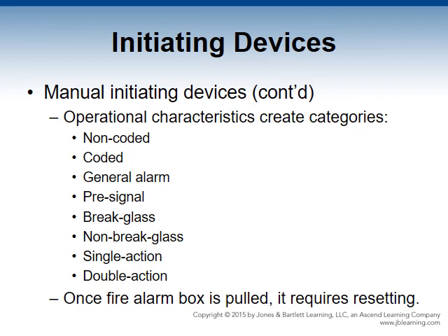Once a fire alarm box is pulled, it requires resetting. The fire alarm system will usually not reset until it is back to a normal or ready service. Usually the box must be opened, often with some sort of special key or tool, and then a switch may be needed to reset or a rod may need to be replaced. Oftentimes you can find these components somewhere near the control panel or sprinkler head box.